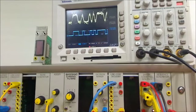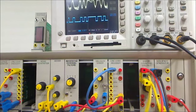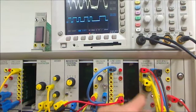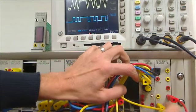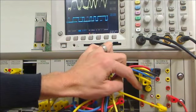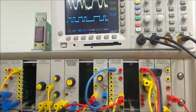So using the bit error rate instrumentation, we can actually count the number of errors by using the bottom half of the utilities module. It acts as a gate. It allows you to count the number of errors for a certain number of clock cycles, so that you can take measurements of your error rate as a ratio of 10 to the 3, 10 to the 4, 10 to the 5, 10 to the 6 clock periods. So you'll have a well-expressed bit error rate.